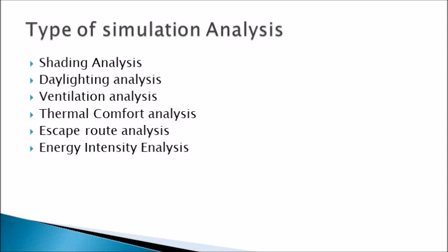Ventilation analysis is another important aspect of simulation, but normally you require a special engine. Engine is the algorithm or the calculation being used by the simulation program. Ventilation requires quite heavy calculation, because you need to understand how air moves through your buildings, if you provide openings or if you provide mechanical ventilation from your outlets, how the air travels throughout your building or throughout your room.